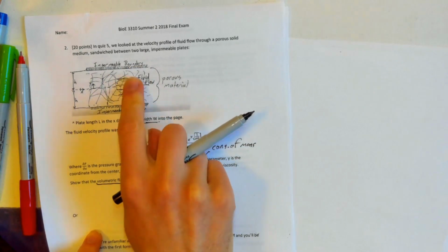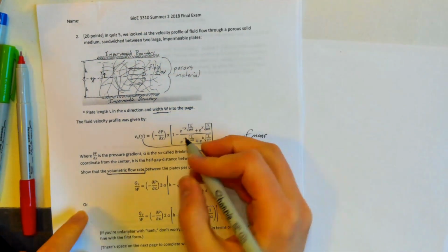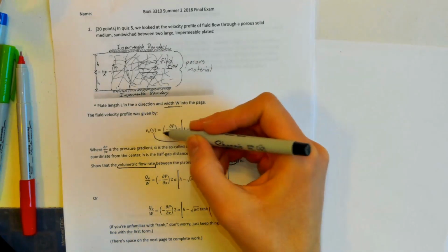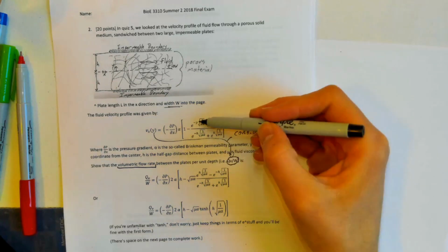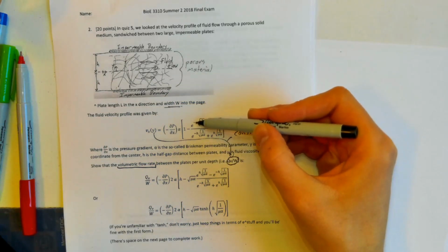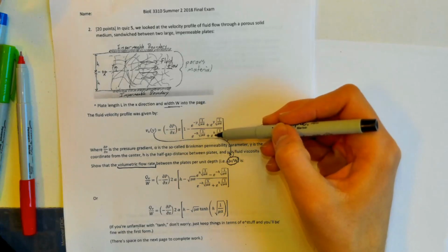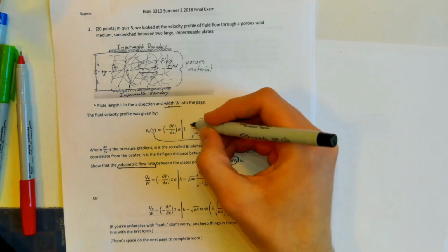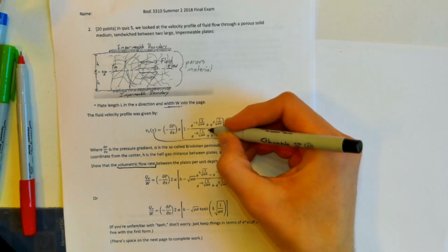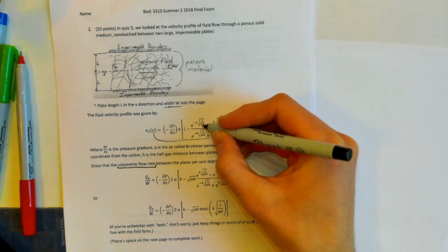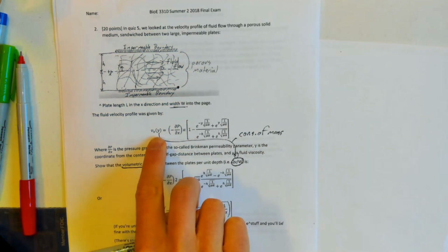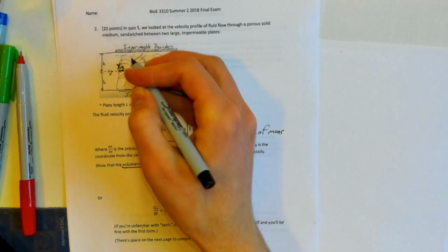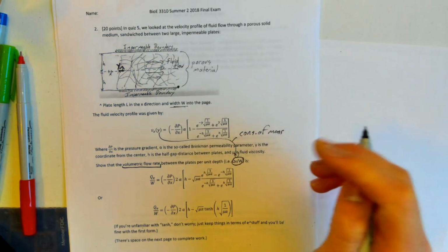So here's just a side view of what this flow might look like. This y velocity, if you'll notice, if I evaluate this at y equals minus h, then I have minus h right here, which is h, which is the same term as this on the bottom. And if I put y equals minus h right here, then that's the same as this on the bottom. So then this whole term, if I evaluate it at minus h, ends up being 1. So I have 1 minus 1. So I essentially have 0 velocity at y equals minus h. If you noticed, I've defined y to be in the center line of this plate, right?